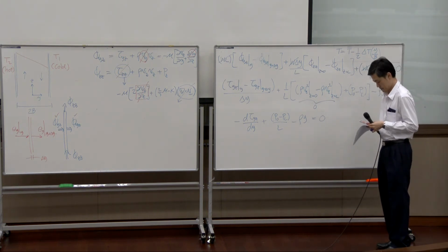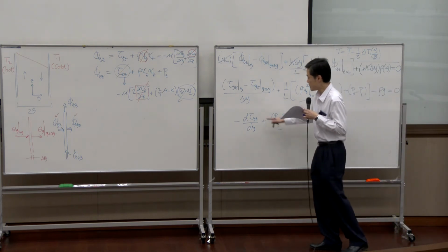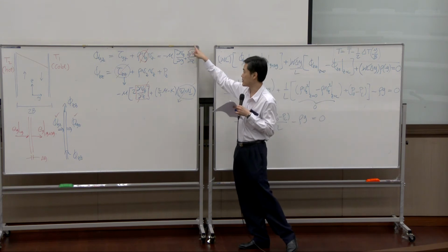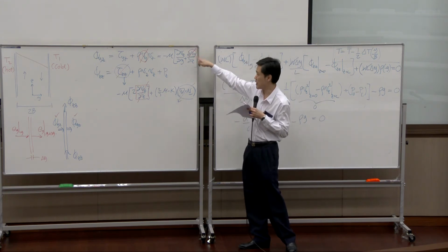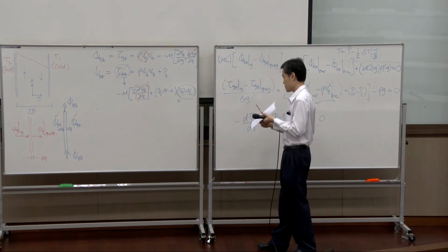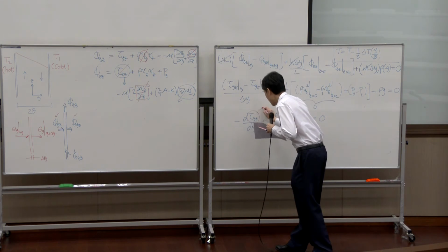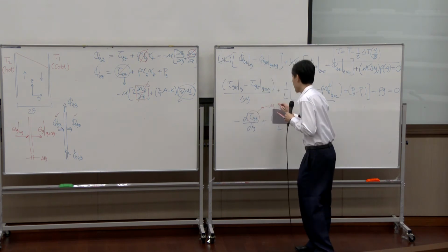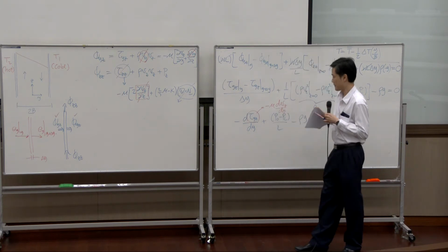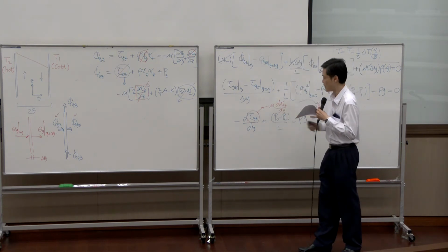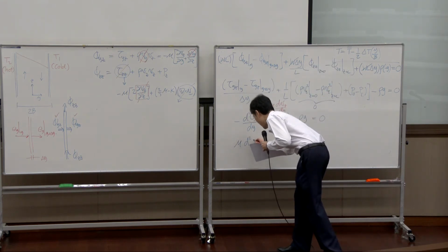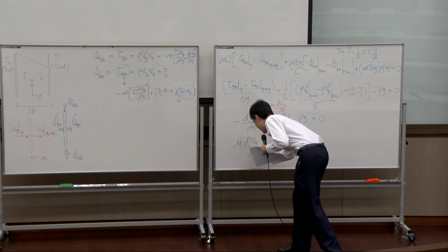And if I replace this tau by Newton's law that we determined earlier, where the second term is already eliminated, tau itself is minus mu dvz by dy. Plug it back here, minus and minus cancel out. I get mu d square vz by dy squared.